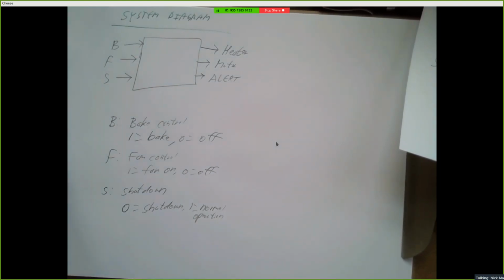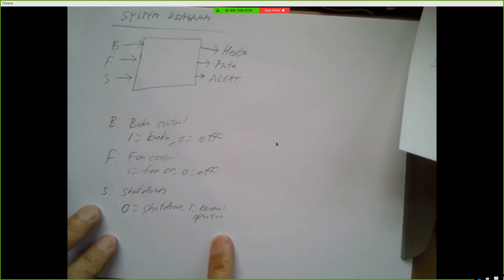So I have to have current going into my system in order to generate this signal 1 which says everything's okay, keep baking. But in reality, the only reason I'm doing this is just to show you why it's important to specify what a 0 and a 1 mean. Because we don't have an inherent sense of what a shutdown signal should look like. Should it be a 1 or a 0 to shut down? Other than the fact that I called it shutdown. If I called it run, maybe a 1 means run, 0 means don't run. So spec these out.